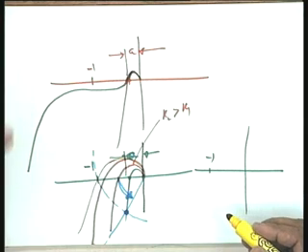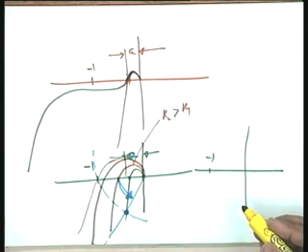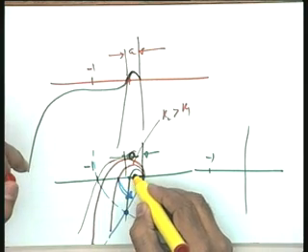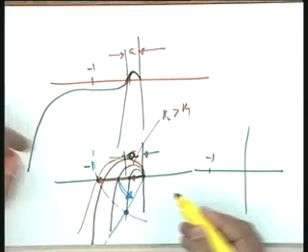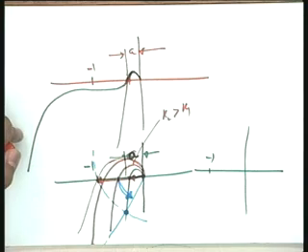Can you tell me by what factor I can increase the gain so that the plot passes through the minus 1 plus j 0 point? I repeat my question, by what factor can I increase the gain so that the plot passes through the minus 1 plus j 0 point? 1 by a, obviously. Please see, if a is the intersection here, you want this magnitude at this particular frequency, this is one vector, at minus 180 degrees. So, this will pass through the minus 1 point, it means the k is to be elongated by this much factor, which is equal to 1 by a.